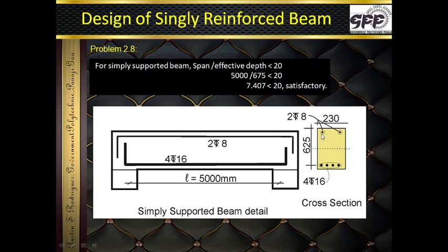If we don't provide this all-round bar over here and suspend these, obviously these 4 bars will be lying down over here. Giving the cover would be extremely difficult. So that's why these are called the hanger bars. Hanger bars are generally those bars which are of very small diameter.